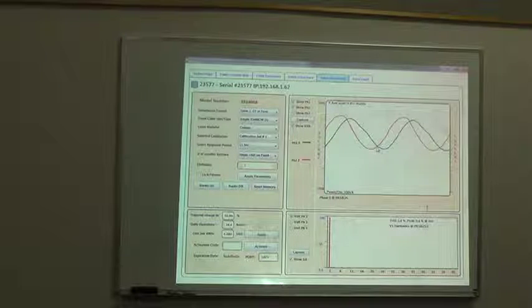And they have it all nicely broken down. Not every power company has that. That's why it showed up, because I don't get that every day, where they have it actually nicely broken down: the delivery charge, demand delivery charge, kWh delivery charge, supply charge. Because I have it all broken down, you know exactly where the saving comes from. When you correct for the negative energy, you're essentially saving the electric company money, so it doesn't cost them as much for delivery.